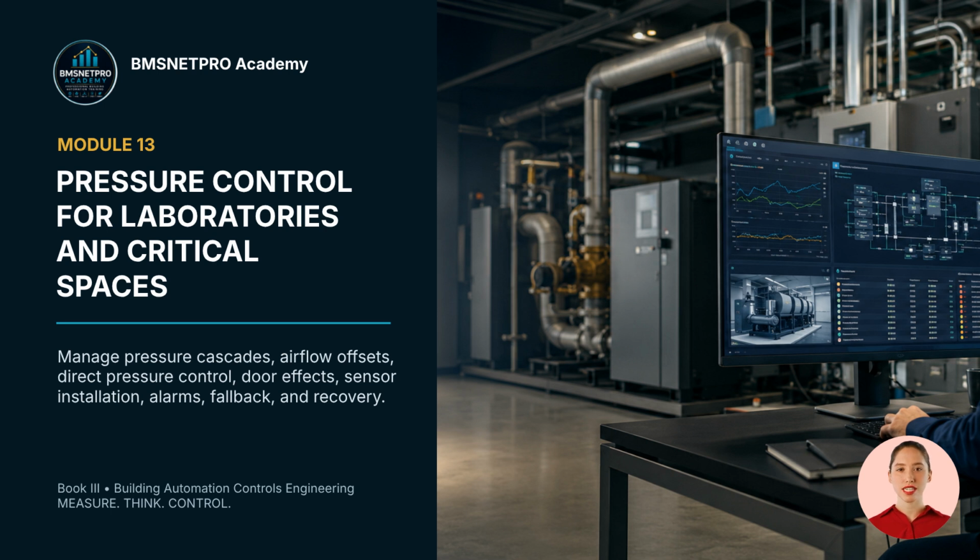Welcome to Module 13, Pressure Control for Laboratories and Critical Spaces. Pressure control protects airflow direction. It must be designed around leakage, doors, supply airflow, exhaust airflow, sensor installation, alarms, fallback, and recovery. In this module, we will separate pressure set point from the real objective, maintaining the approved directional airflow relationship under normal use, door operation, and failure conditions.